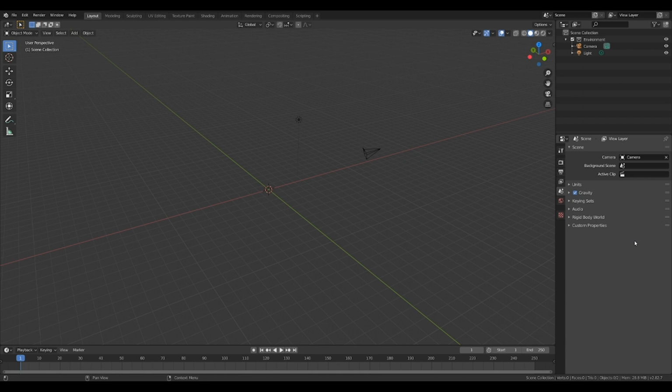So you basically have 2 really small height cylinders on the bottom, which are the base of the old well. You have these columns, which are nothing more than cylinders that are very tall, yet not really thick. So 6 of those. And then you have that dome on the top, which is nothing more than half of a sphere. We're going to literally be using those 2 shapes to make the entire old well. We're not going to make the drinking fountain in the middle. That will be a little bit more advanced, so don't fret too much on that side. So let's start with the base of the old well.